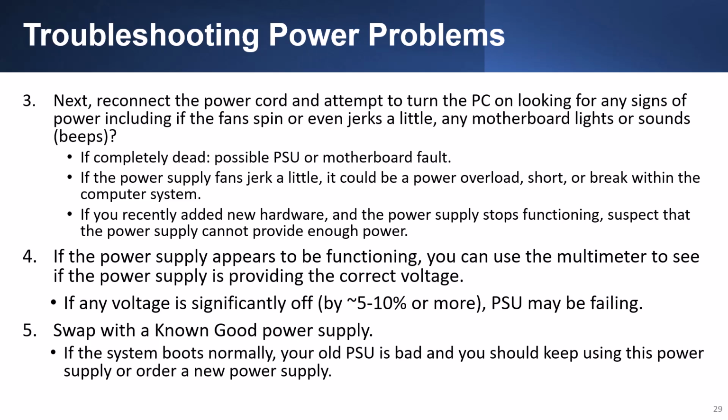Swap with a known good power supply. If the system boots normally, your old power supply is bad, and you should stop using the power supply or order a new power supply.